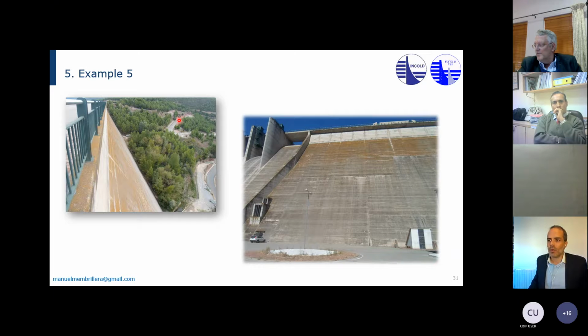And so what we did is we placed a rock fill with gravel and essentially an inverted filter here. So this is all covered with an inverted filter that is protecting against any kind of erosion from happening, and water is just flowing and it's collected, and the seepage goes down here, and happy days.